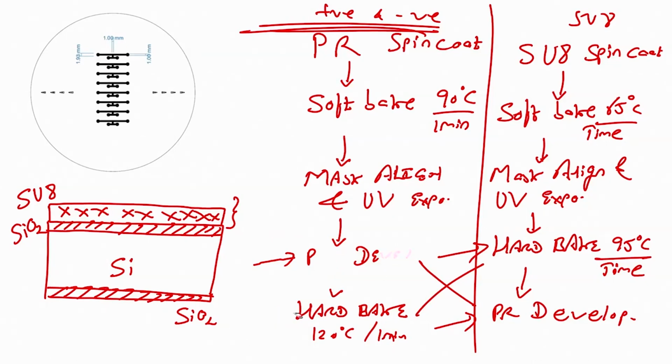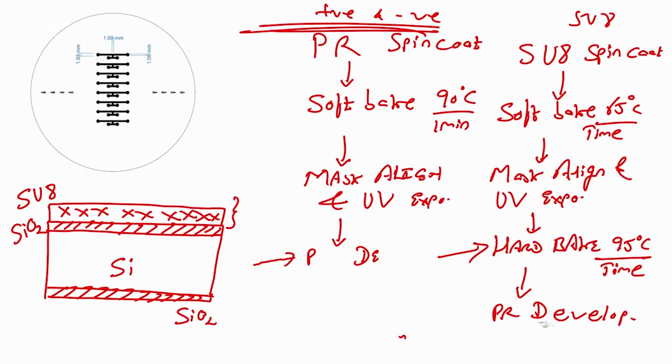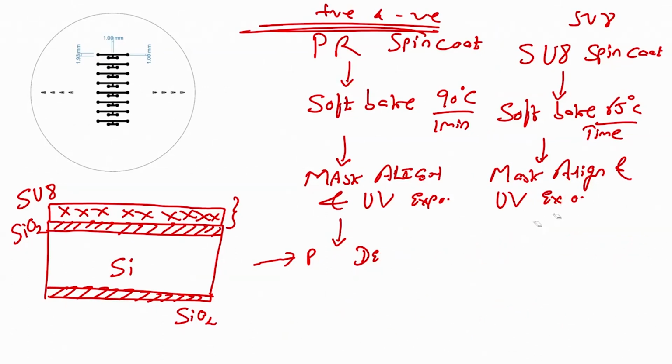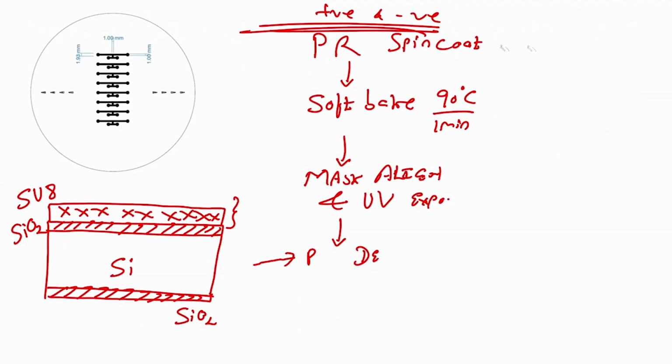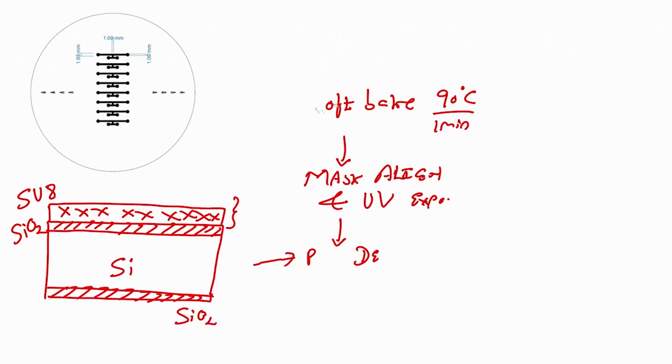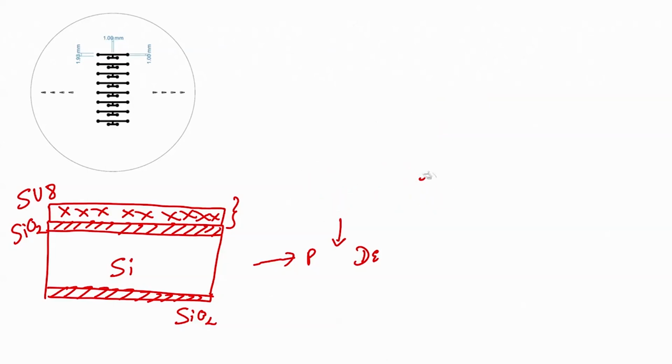The advantage of using SU8 is that we can get SU8 of different viscosity, and thus the thickness of the channel can be different. The SU8 is easy, first of all, because it is just photoresist that we have to pattern. Second is that the thickness can be varied depending on the type of SU8 that we are using. There are several types of SU8, SU8 25, SU8 50 and a lot of others depending on the thickness that we want, all right.